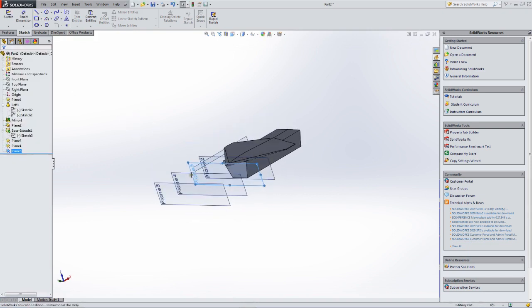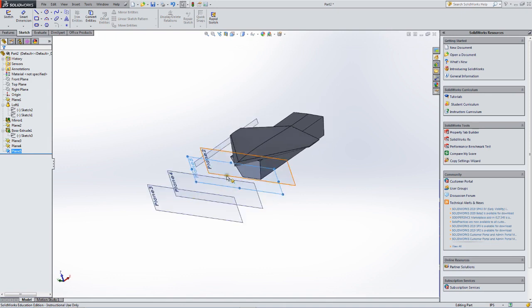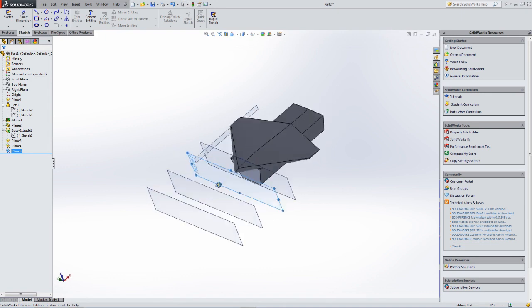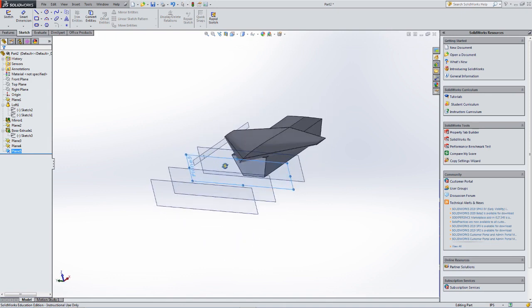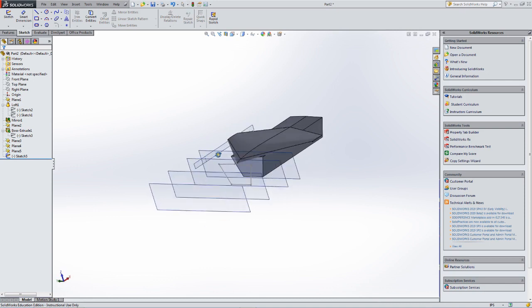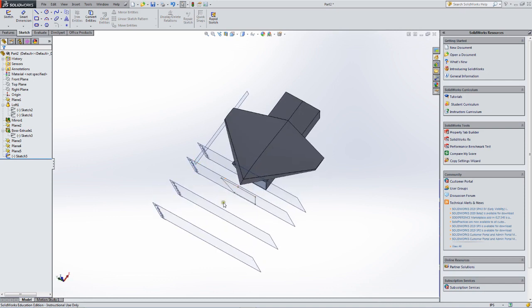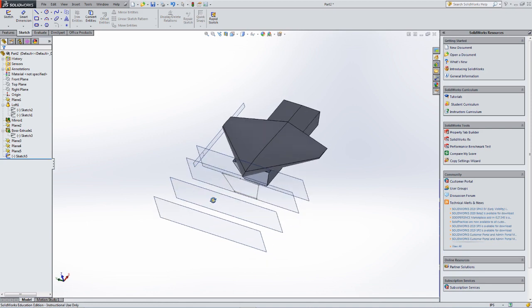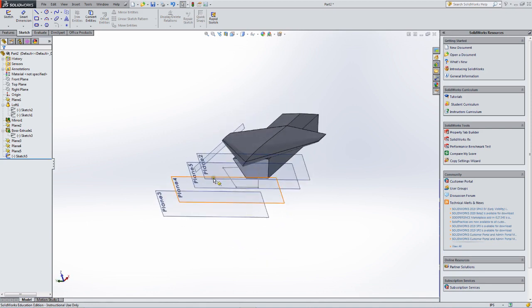I'm going to start the first fuselage frame here in plane 5 as being an exact copy of sketch 3. So I'm just going to Control C, click on the plane, Control V, that's our sketch 3, and I'll loft it. Then we'll have to narrow down so that there's a place for inlets, and then narrow down again for the nose. So let's do that.